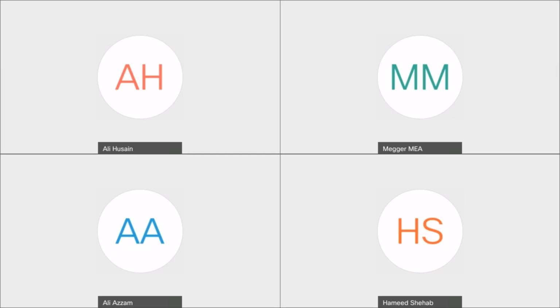So at 50 ampere or at 100 ampere, the difference is that the voltage being generated or applied across this contact link, whether it's a contact or bus bar or joint, will correspond to the injected current. So the voltage will be double for 100 ampere compared to 50 ampere. But the resistance value should not change. It will not be different. So the value itself will not change a lot.